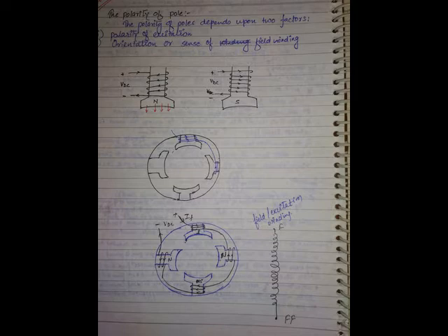But these eddy currents will not circulate as freely as they were circulating here, and finally you are reducing the eddy currents. In any meter or anywhere, if you see laminations or strands, it is to reduce eddy currents. You are making thin sheets of 0.4 to 1 mm. This is the thickness, 0.4 mm to 1 mm.